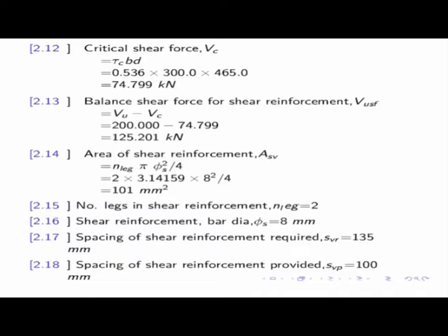Now the balance shear force we are having is 125.201. That means for this I have to provide the stirrup, because for this additional shear, we have to provide stirrup or shear reinforcement.